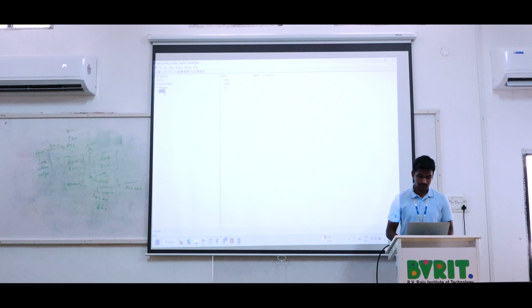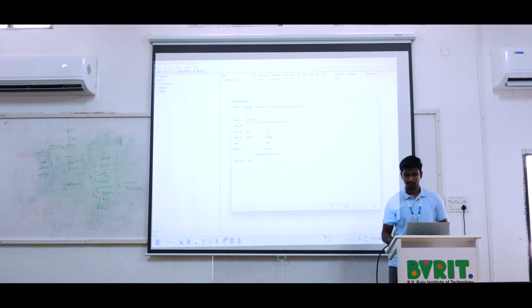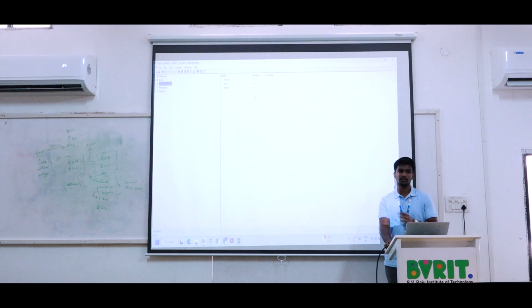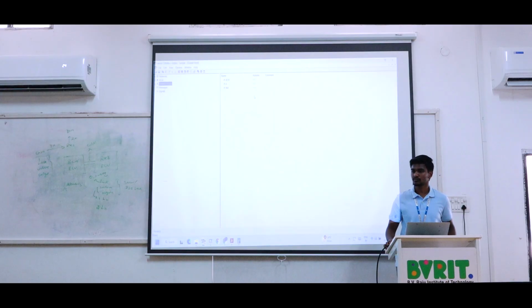First we can go to signals, and then right click. Sir, wait. After we receive text, IC, instrument cluster is IC. You can take one more, because as per requirement we are able to transmit signals and receive signals by different kinds of ECUs also. Okay. So move to signals.